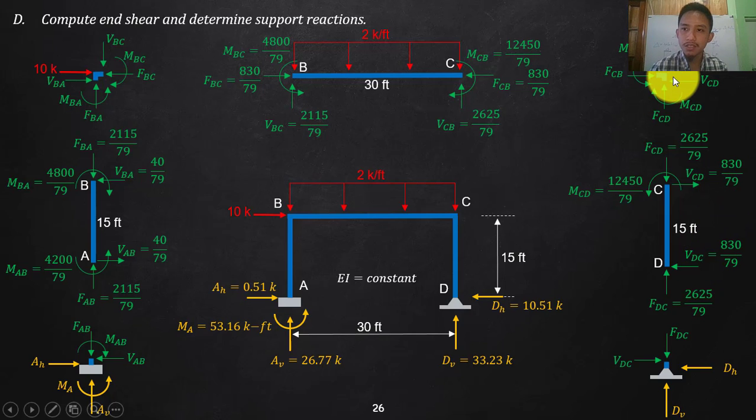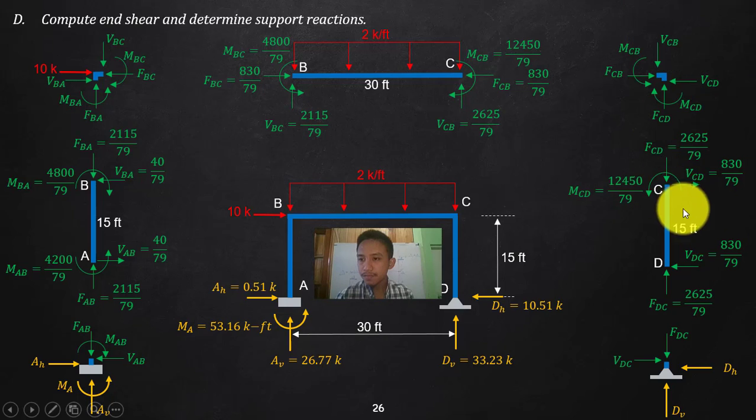Now transfer at the joint to get your action forces, since we will need that one for reactions. So this is going up, that will go down, which is your action here. And in this one, this is going up, transfer there, going down, that will be the same as your action here, which is 211.